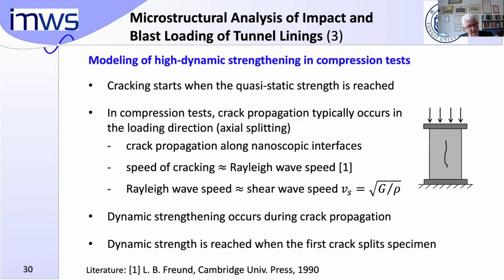Let me now say a few words about modeling of high dynamic strengthening in compression tests. Cracking is assumed to start when the quasistatic strength is reached. In compression tests, and I'm restricting myself in this lecture to compression tests, crack propagation typically occurs in the loading direction, and what happens is actual splitting.